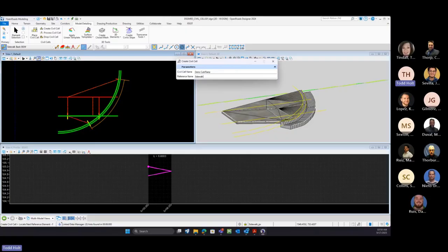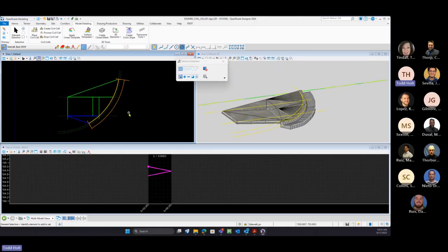And then our last name, sidewalk back. And that will be profiled as well. All right, so it's going to grab everything. We should see the 3D mesh components get selected as well. Once we have everything selected, we're going to do a right click. We don't have optional references. We're going to right click and then we'll left click, and that's going to create our civil cell.